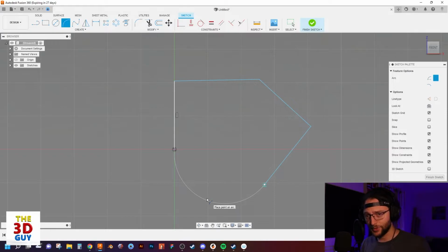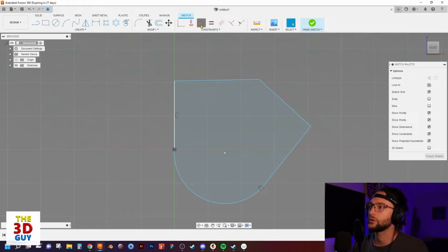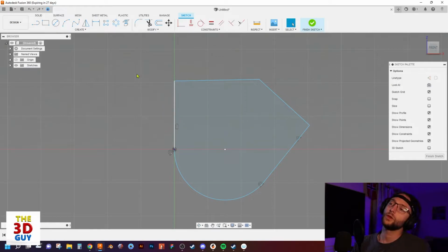And when you're setting up these sketches, typically that is something that you can be doing as you're creating these lines, is auto-generate these constraints. So keep an eye out for that. So in this case, you can see I've made a tangent right here. I did not here. And so we're just going to click on tangent and create that, and it's kind of locked that in. And again, if you want to get rid of any of these, you just click on the constraint. If you can't see the constraint, sometimes you actually have to click on the point where the constraint is and then delete that.